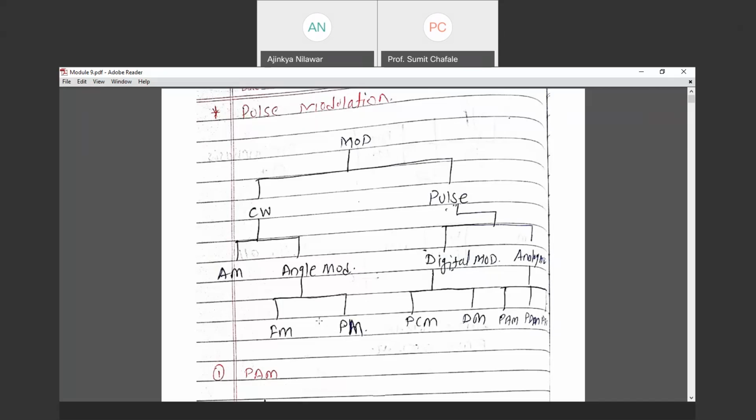The second thing we can adjust is frequency. That means the width of that particular signal on the x-axis we can arrange. If you increase the time per division knob, the signal on the CRO shrinks, and if you decrease it, the signal expands. Shrinking and expanding is nothing but increasing and decreasing the time period. Time period deals with frequency, as T is equal to 1 by f. So any signal has three attributes. First is amplitude, second is frequency, that means the volt per division knob and time per division knob.